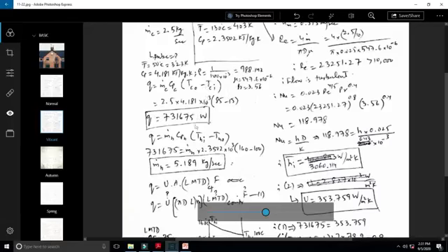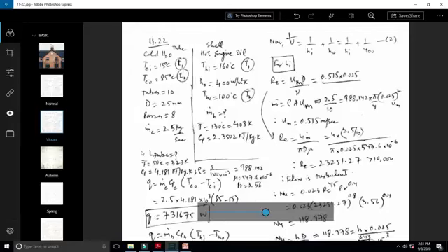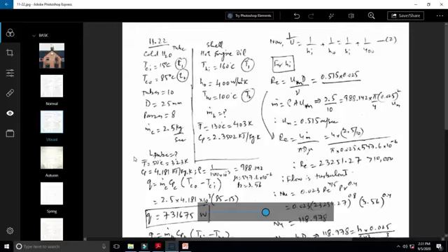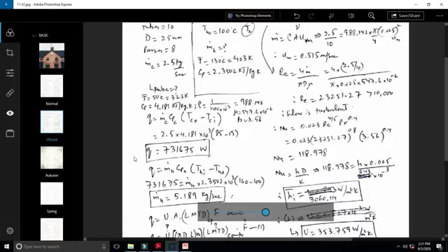Now, so we have found out the mass flow rate of the hot fluid, which was one of the unknowns. The second point is to find out the length of the tube through which the cold fluid, which means water, is flowing. Now the length means finding out the area, right? And area would be found out using Q = UA delta T.